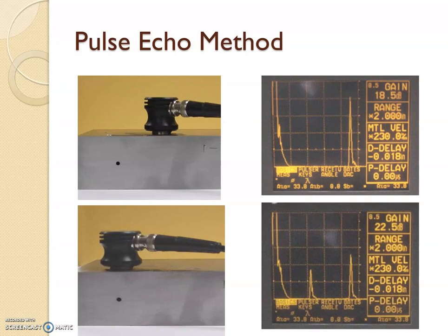The pulse generator generates high frequency waves and is applied to the piezoelectric transducer, and the same is recorded in the CRO. So after initiation, a pulse will be generated first. Name this pulse as A. It is our reference pulse. The piezoelectric crystals are resonated to produce ultrasonic waves. So the ultrasonic waves are penetrating through the material and it is analyzing.